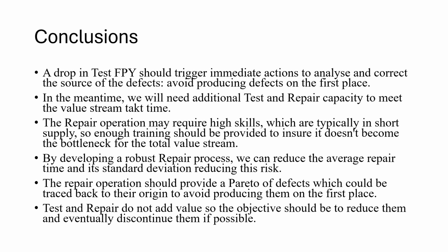These are some conclusions. A drop in test first pass yield should trigger immediate actions to analyze and correct the source of the defects, avoid producing defects in the first place. In the meantime, we will need additional test and repair capacity to meet the value stream takt time. The repair operation may require high skills, which are typically in short supply, so enough training should be provided to ensure it doesn't become the bottleneck for the total value stream.